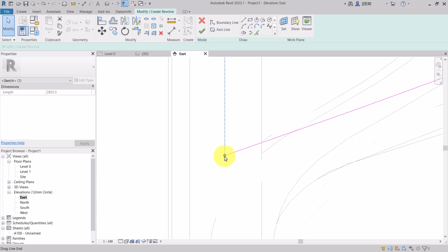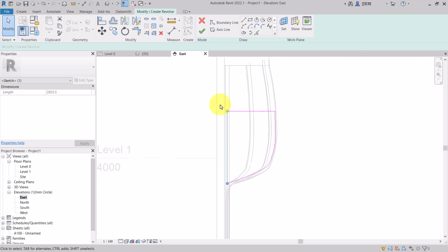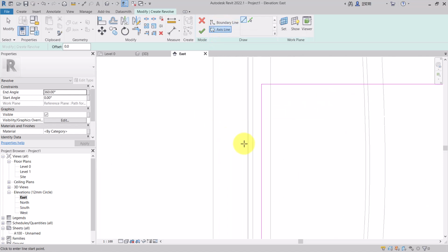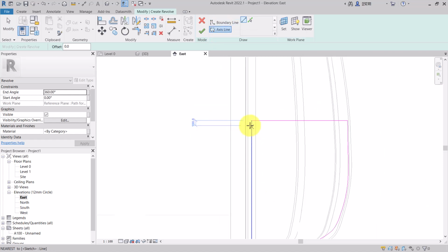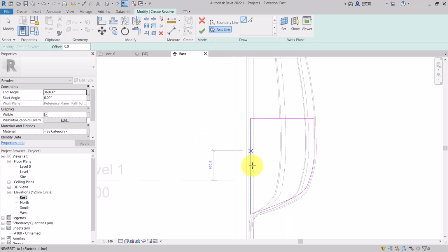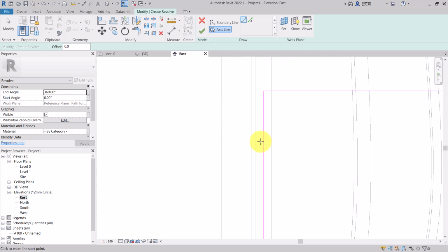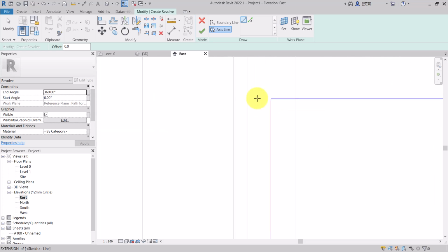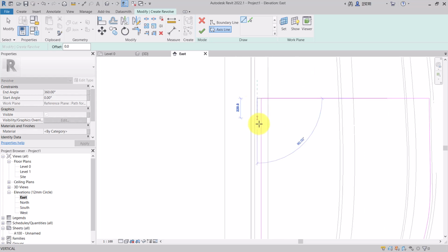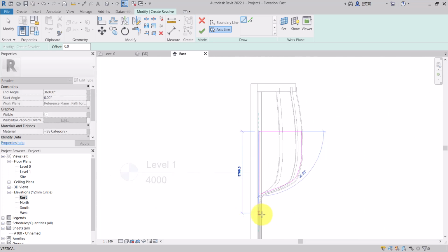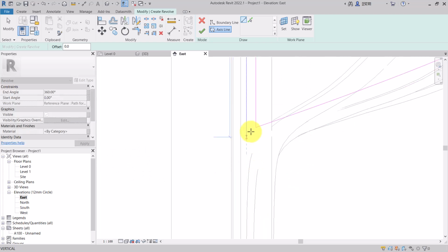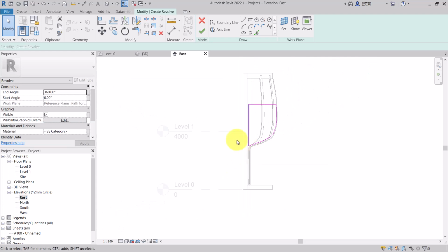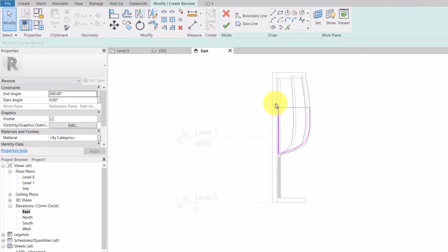Anyway, that's the boundary line, and if it's wrong, we're going to know from the software itself. So we're going to go ahead and select the axis of revolution now. The axis of revolution is going to be a straight horizontal line like this, but don't let it touch the profile boundary that you just finished creating. That's the pink line. So I'm just going to hover slightly to the left, pick one point, and go all the way down to the end of where the boundary actually stops and select the second one. So that's our axis of revolution. Now that's been set, very important next step.